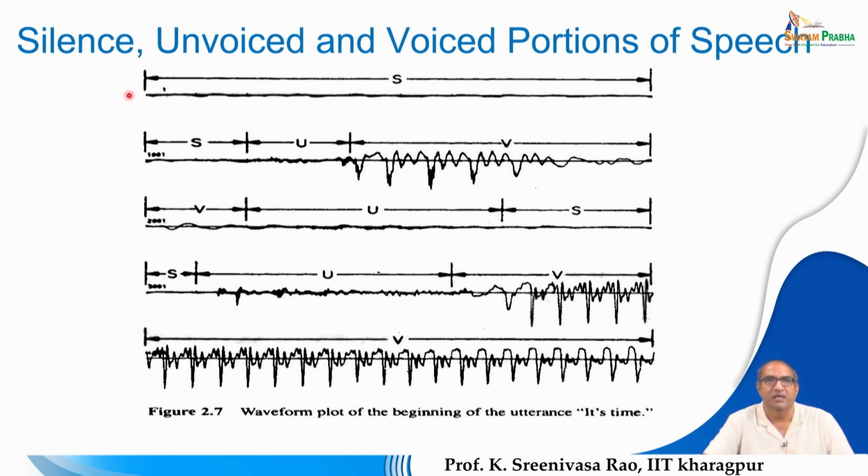The first subplot runs from sample 1 to sample 1000, the next from 1001 to 2000, and likewise each subplot corresponds to 1000 samples, or 100 milliseconds. It means the signal is sampled at 10 kHz, that is, 10,000 samples per second, which is why each 100 millisecond subplot corresponds to 1000 samples.